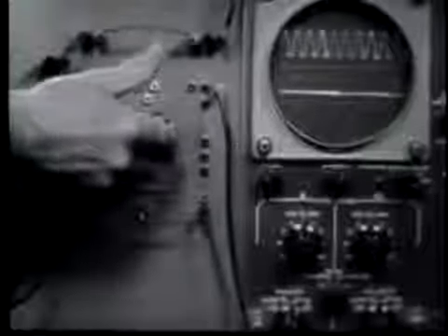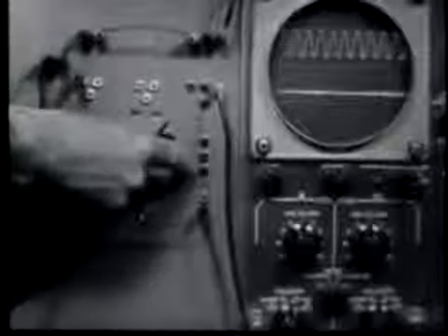The other lead here, the one in the middle, is used to provide a synchronization voltage or an external trigger for the sweep circuits of the oscilloscope. Now, down here, in this circuit here, is where we'll hook up our filter components. This is the series position, and here is the shunt position. Now, notice, as is always the case, the output is taken across the shunt component and is displayed on the B trace or the lower trace of the oscilloscope. Note also that, as we did in the first lesson, everything is grounded together.